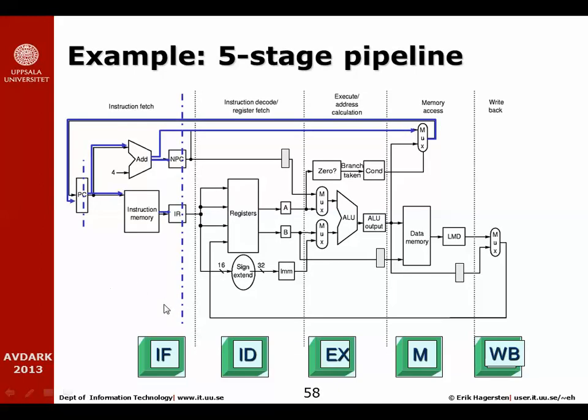What's happening here in the first stage of this pipeline, the instruction fetch stage, is that we will get a value out of the program counter, and that value is the address pointing to the next instruction to be executed. We're going to read out that instruction, those 32 bits representing the next instruction to be executed, and put it in a latch. This vertical bar here symbolizes a latch in the pipeline design. So that value is going to rest here safely in this latch at the end of this clock cycle. As you can also see, the PC+4 value that we added here is going to be looped back all the way through here, and the value PC+4 is going to be put in the program counter. That's the most normal case of the execution.